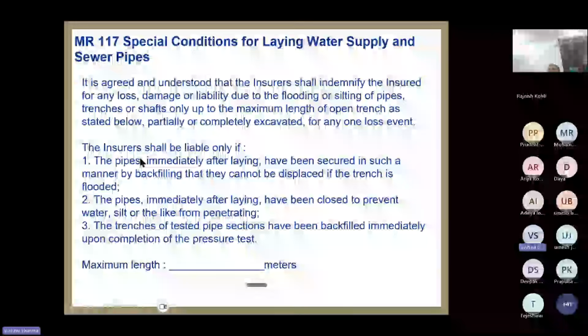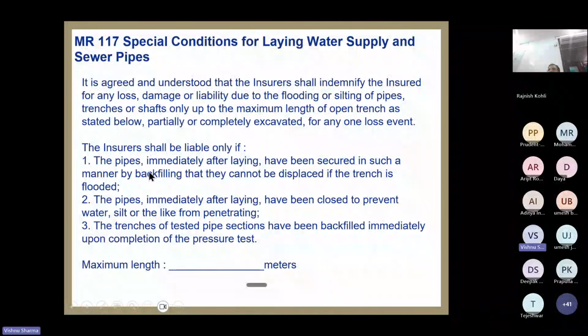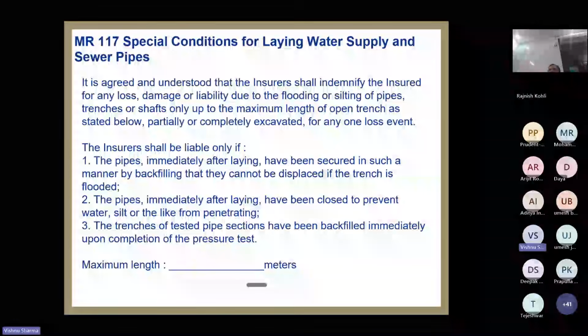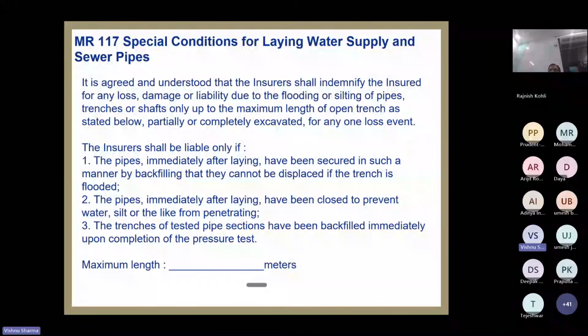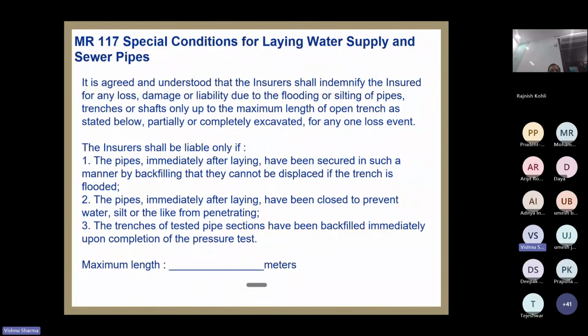This is important. ये क्या वारंटी बोल रहा है? The moment you lay the pipe, तुरंत मट्टी भर दो. Don't keep it like this. Don't keep the pipeline just at the bottom of the trench. Otherwise, if there is a rainfall, it will start floating. Displace हो जाएगी पूरी pipeline, joints खुल जाएंगे. To avoid that, what is recommended? Warranty says the moment you lay the pipeline, fill it so that it is intact, displaced नहीं हो.